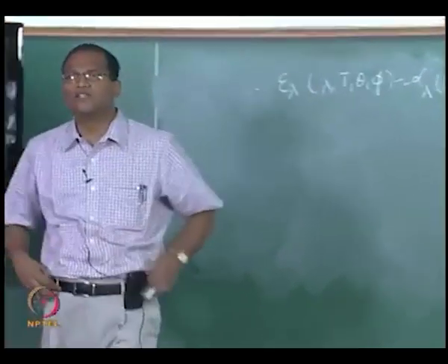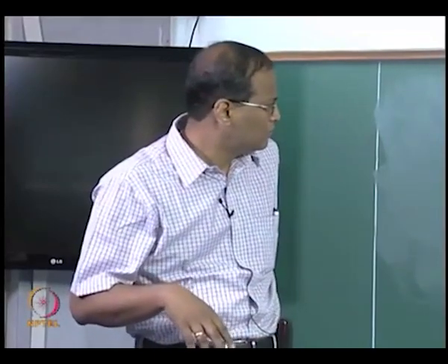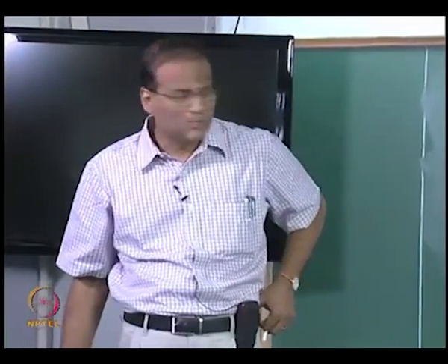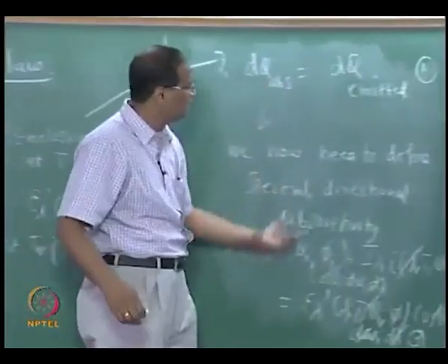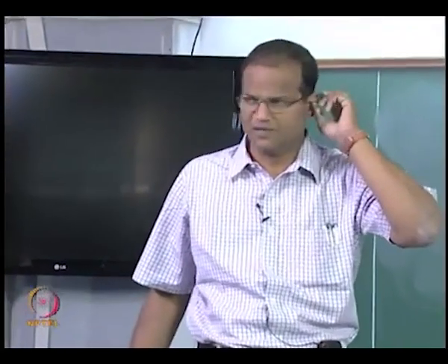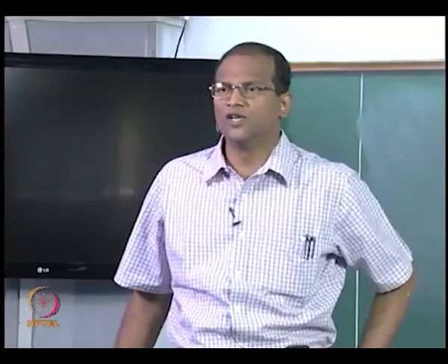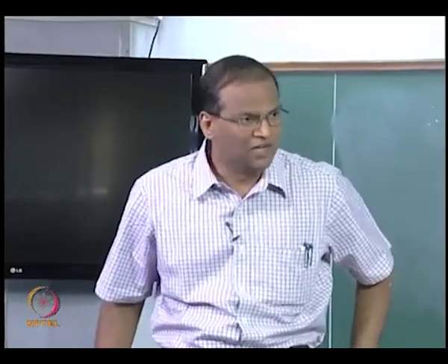It is true regardless of the direction and the, any problem? No, I am writing the expression for dq absorbed and dq emitted. dq absorbed I am writing in terms of the absorptivity, and dq emitted I am writing in terms of the emissivity. Okay. So to cut a long story short, the spectral directional absorptivity is equal to the spectral directional emissivity. This is the Kirchoff's law.